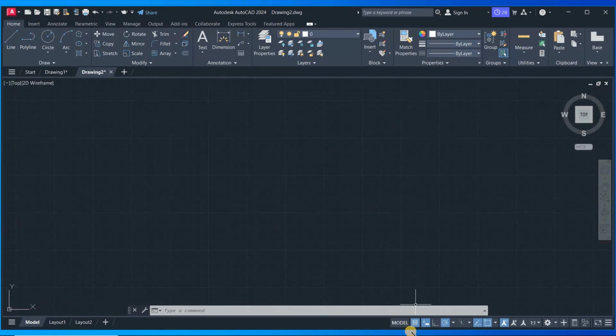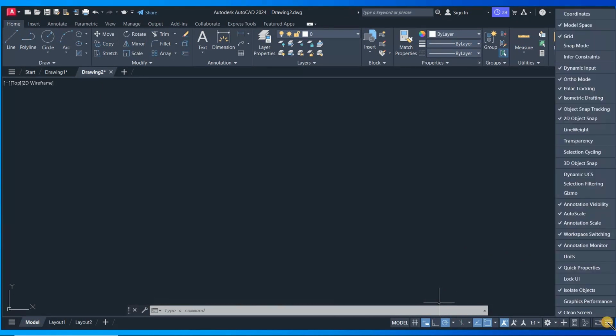I don't want to see grid lines. By a click, I will just disable the grid lines, so I need not go through settings to access the grid lines change option. The same thing applies with the drawing scale, and the same thing also applies with the dynamic input tools.